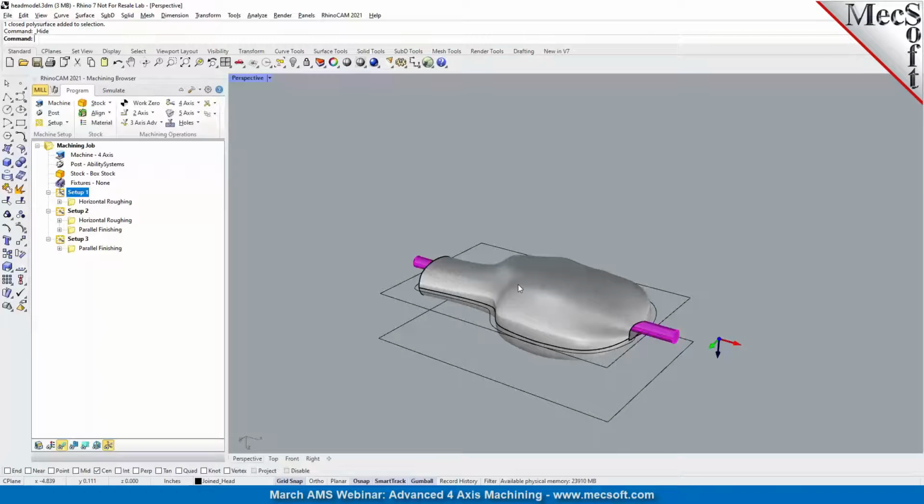Now, the benefit of doing the indexed machining is you just have to zero it out once at your initial orientation. And once you've done it, the rotate table setup and machining it from the other side does not require you to create multiple origins or multiples.